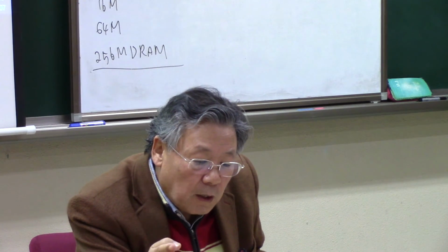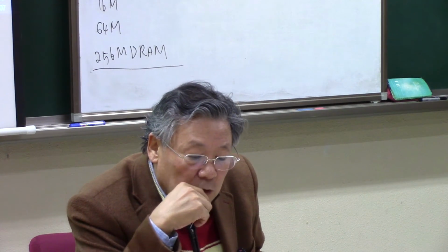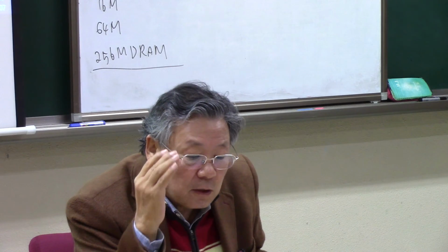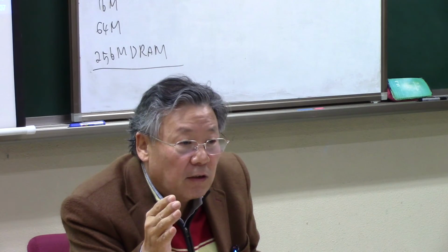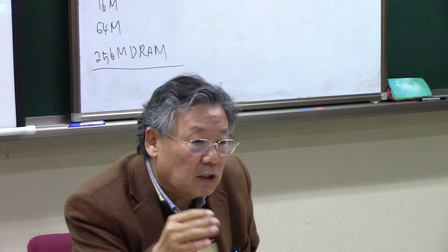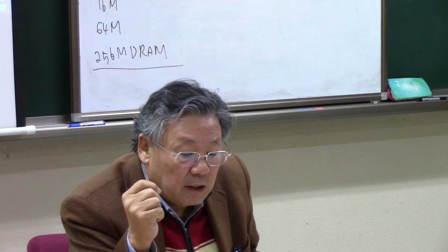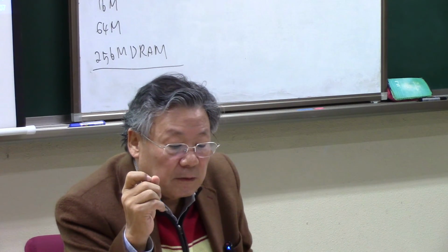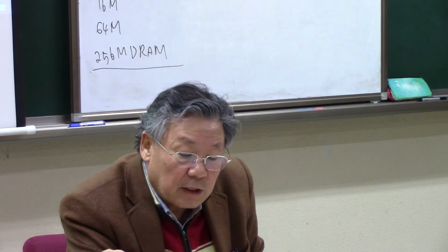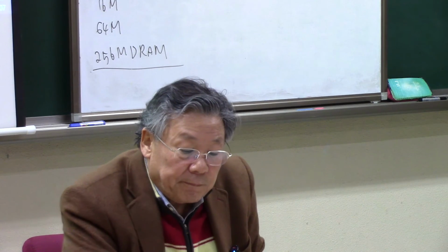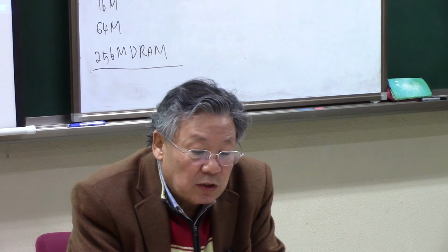So you have to simplify the processes to have a high yield, okay? The process number and the circuit density, defect density, of course. If you can reduce the defect density, then the yield becomes high. And finally, the crystal defect density, okay? Crystal defect density is related to single crystal growing. Okay, and these are the yield issues, and yield issues are very important.